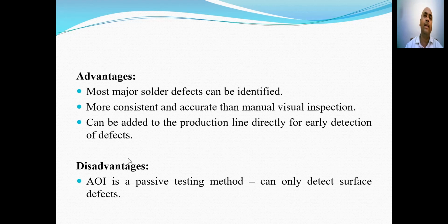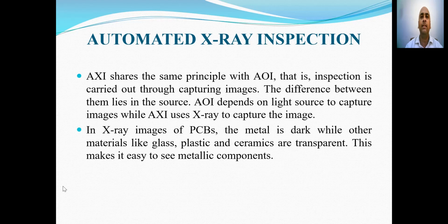The disadvantage of AOI is that it is a passive testing method. That is, it can only detect surface defects. It cannot tell about the performance of components, or some shorts or opens which are present on the PCB. The next in the series is the automated X-ray inspection method.